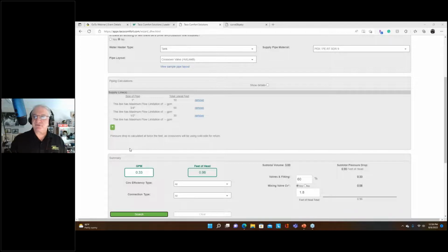Monday, 6 a.m. Tuesday, 7 a.m. So what it's going to do the following week is Monday, it's going to start pulsing that 5 on, 10 off, 5 on, 10 off at 5 a.m. Gives me a 2-hour window from 5 to 7 on Monday in case I get up a little early, in case I get up a little later, or in case there's a time change. So I have that time built in for those 2 cycles in that other example to make sure I get that hot water line primed.